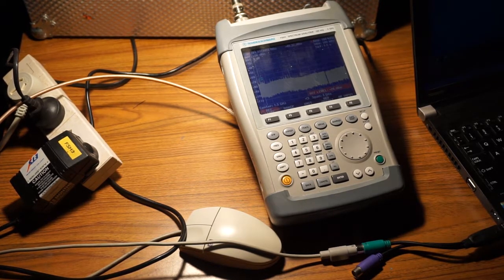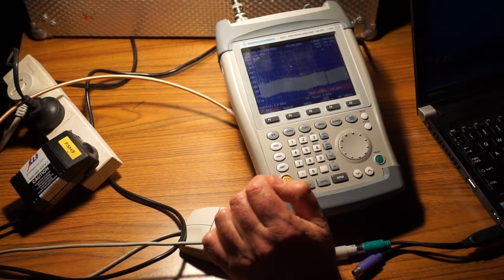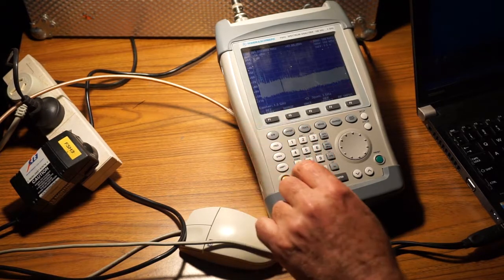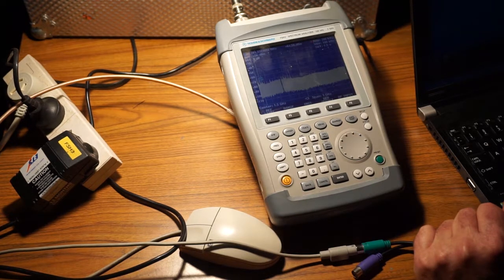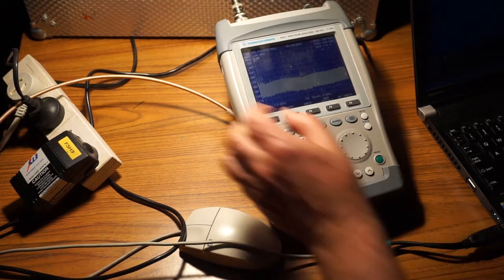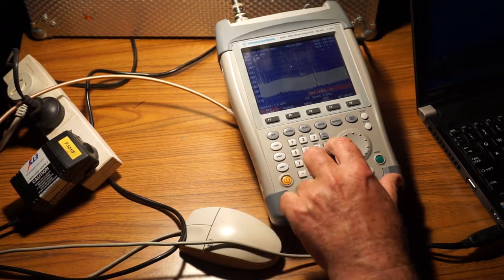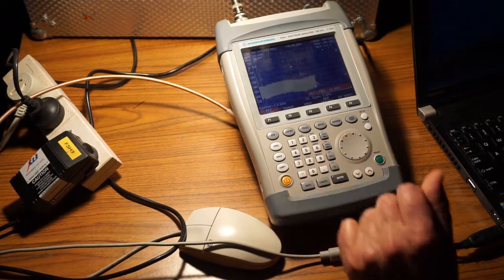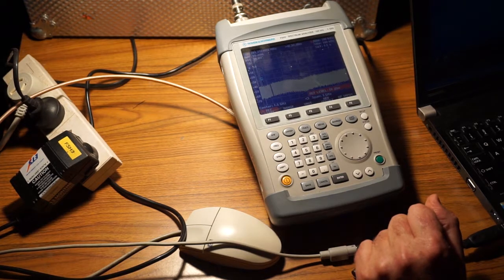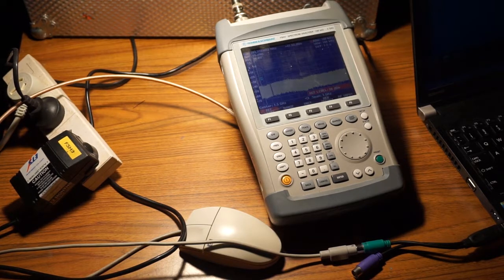And so what we can do, zoom into this, we can change the reference level if we wanted to. Make it go to say 40 dBm. And it's done nothing. Reference level, minus 20. 40. So Amplitude's adjusting the input attenuator, or it's just affecting the screen? Yes, it'll change things automatically. So that's changed the top scale, now it has gone to plus 20 right at the top, and so everything's been dropped into the noise.